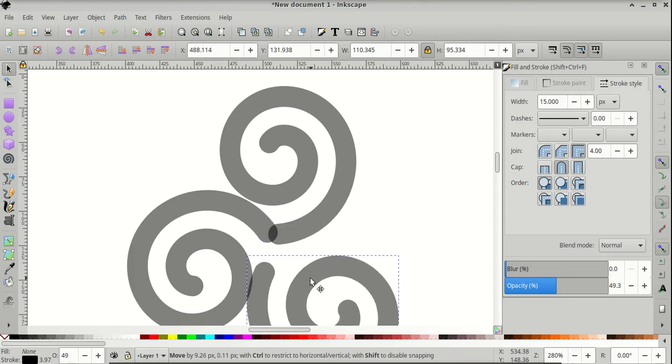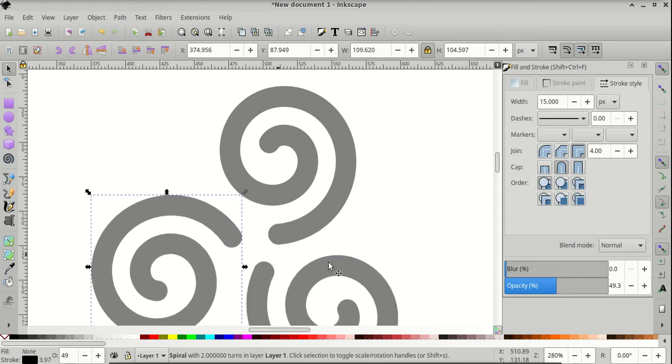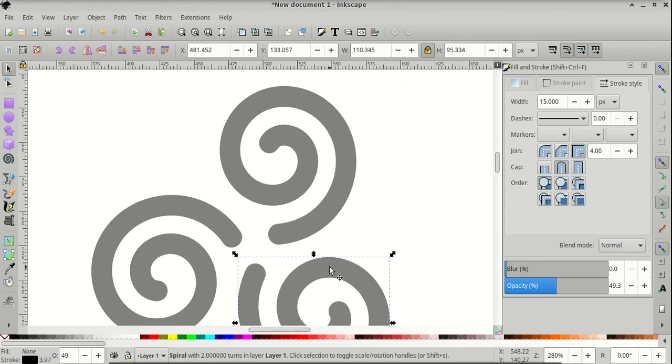So we'll need to create a triangle to space them out. Before we create our triangle, let's come over to Enable Snapping and enable Snap Nodes, Paths and Handles, and Snap to Cusp Nodes including rectangle corners. Once you have those 3 properties set, come over to Create Stars and Polygons.